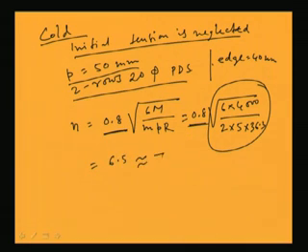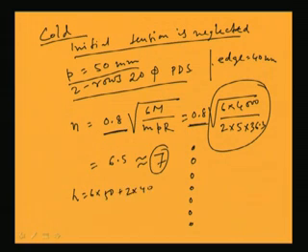That means you can use the number of rivets per line as 7, right. So, if we use total number of rivets as 7, then how will we make it? Let us see. 7 means 1, 2, 3, 4, 5, 6, 7. So, the total depth H will become how much? That means 6 into 50 plus 2 into 40. So, total depth will become 380 mm. So, the dimension of the connections can be decided from this, that 380 mm we are going to decide.